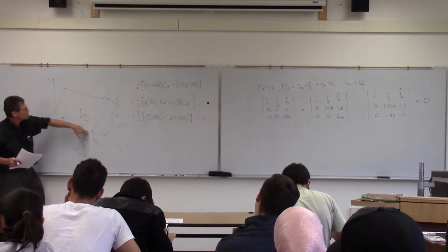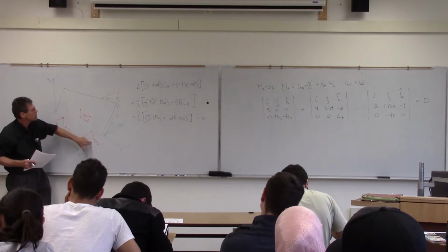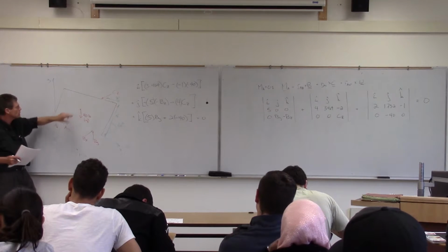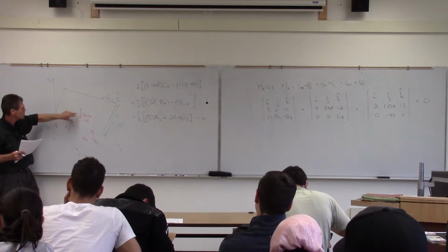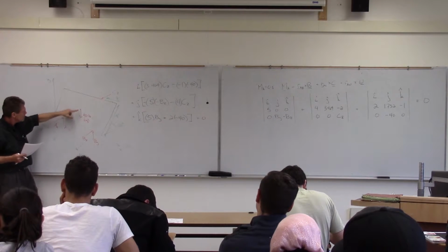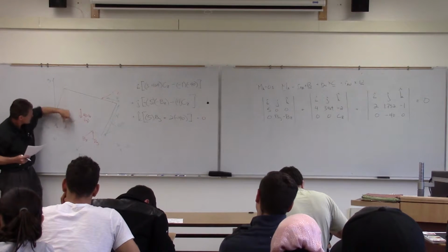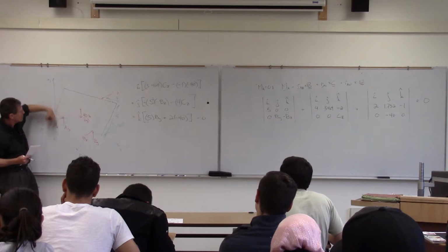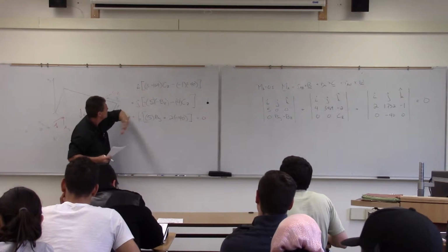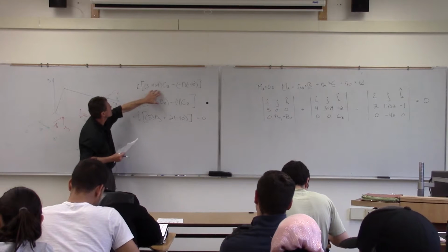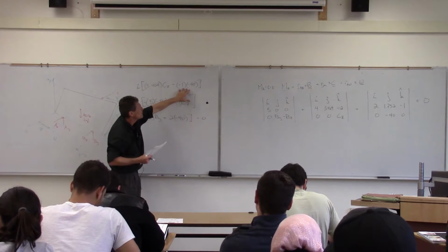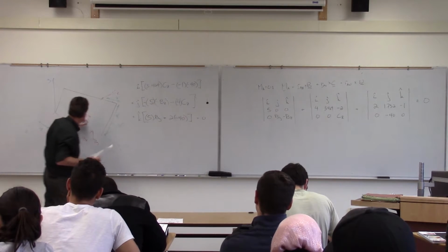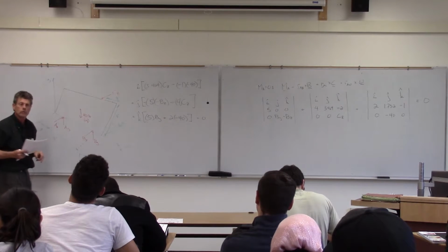So BZ will not participate. I don't see any BZ or BY in there, right? Because it's on the x-axis. That's not going to contribute. My 40, well, let's think about that. If it's going to twist, then it's got to be that perpendicular distance along that z direction there. Where am I? Yeah, the 40 here. So it's -1 over, and then the 40 pounds down.